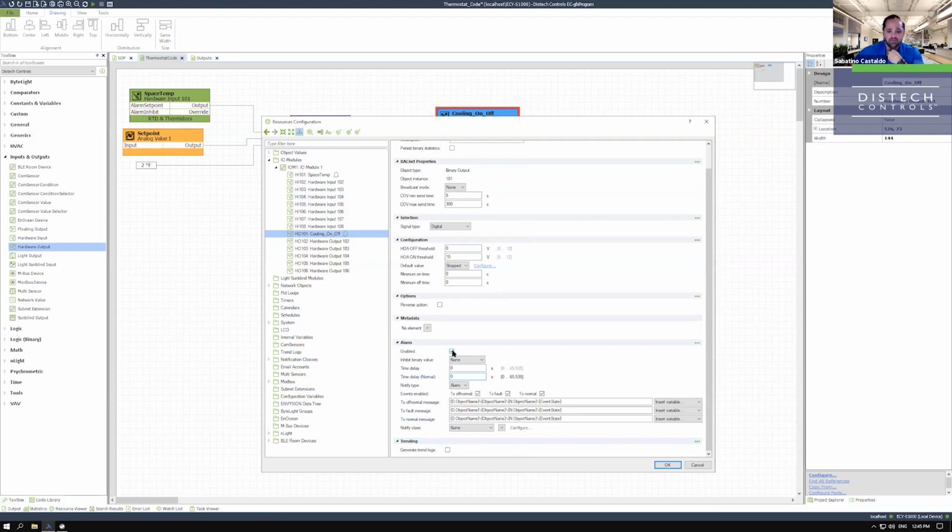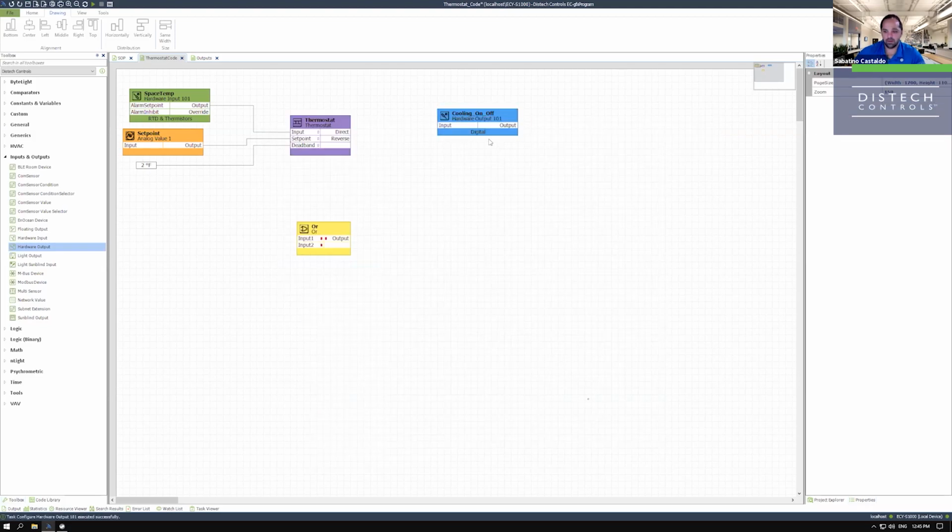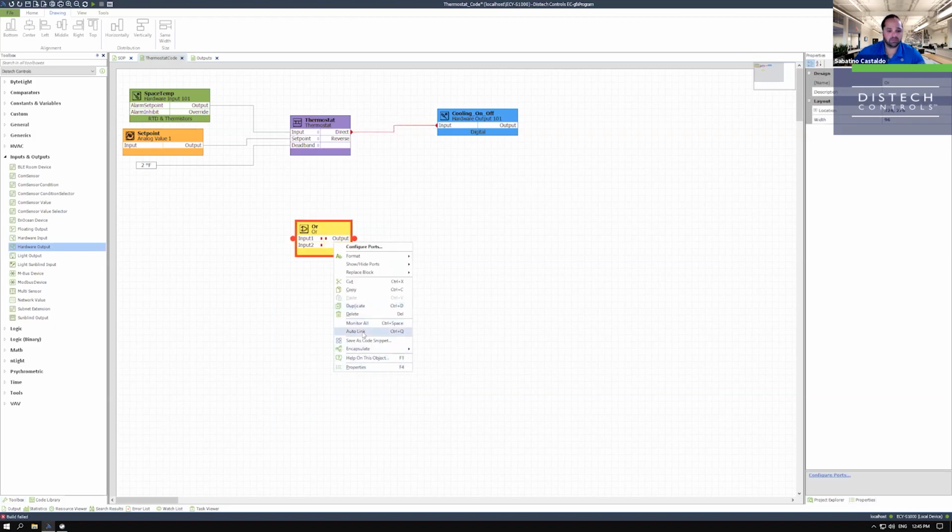And once we do that, this is going to look for off normal to false and to normals. If you want to go with something more elaborate, you could maybe bring it into a binary value alarm to see if it's running and not supposed to be running, etc. You could build that logic yourself as well. So here we go, direct connection. And we've basically built